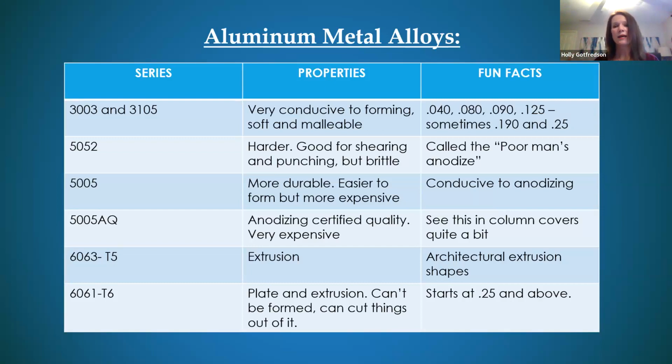With the liquid paint, you're going to have more control over the process. A lot of manufacturers have adapted cleaner ways of painting. I know we have. We'll talk about that in just a little bit. But that's going to be an applied extrusion coating that's going to be applied through E-stat guns. And that's going to last a super long time. It's not nearly as harsh on the environment, and you're going to be able to get a warranty with that. And it also doesn't require something like an anodized quality level of an alloy. And then finally, the 6000 series is going to be primarily for extrusions and curtain walls.